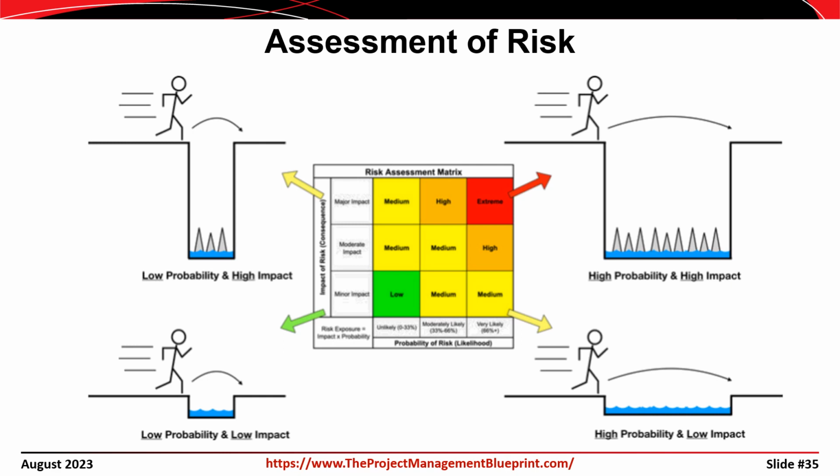So the likelihood of a failure is relatively small, and in the case of a beam, the consequences of that failure are relatively limited. But if we consider the consequences of a failure of a column or something that's in the load path of a structurally determinate system, then that could bring down the entire system. So the consequences of that failure are rather severe.